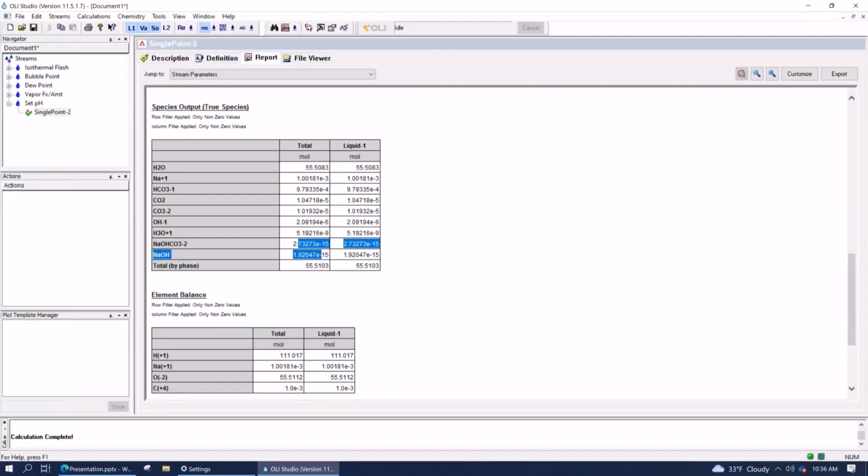I'll give you an example to illustrate my thoughts, AJ. If you have a sour water system and you inject amine, let's say MEA, a significant portion of that will react to terminate, and it will produce some acid sour species, and there is a remnant of the MEA ion that is still in the water, and some of it will be entrained in water and hydrocarbons.